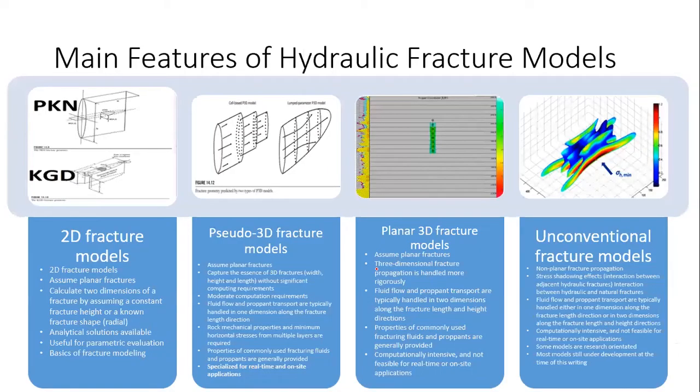And simply that is the main approach, the main timeline for hydraulic fracture modeling over the history. It started with the 2D fracture model, then the 3D model, Frackade and FracPro, cell-based and lumped-based. Then the planar 3D model, GOHFER, and there are more advanced fracture simulators than GOHFER, but they are not flexible like GOHFER. They are not practically used like GOHFER.